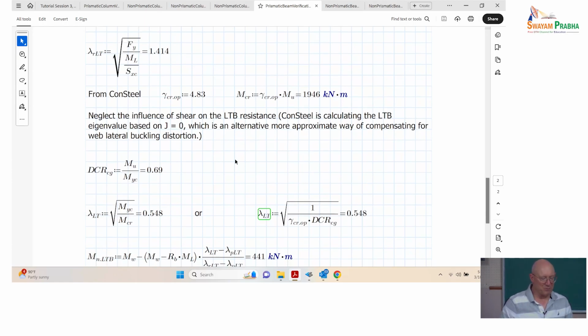Now, if you caught what I was showing you last Thursday night, or what I showed you a little bit yesterday with the flexural provisions that are moving forward: in the current AISC specification, if it's a slender web, we calculate lateral torsional buckling strengths taking J equal to 0. We don't account for any contribution from St. Venant torsion. I think AISC and the U.S. bridge standard are the only ones in the world that are doing that.